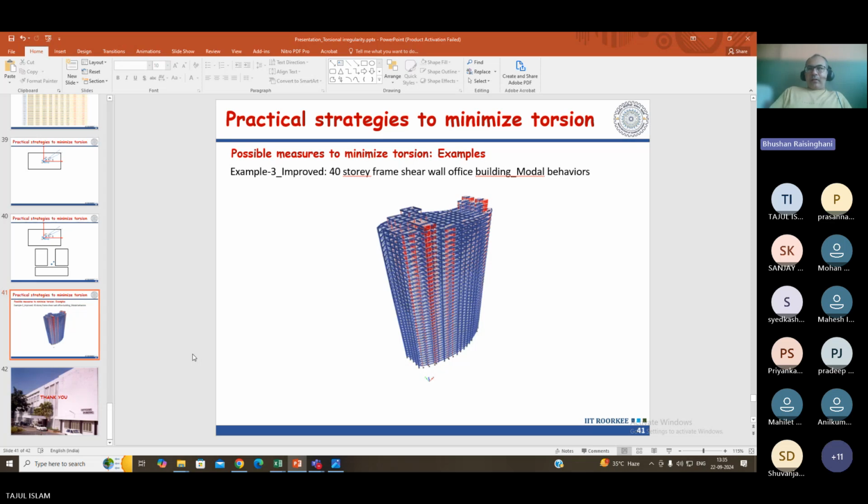I would add this. Our beams and columns are 2D elements, and the shear wall, though taken as a, let's say, pier, mostly works as a 2D element, not as a 3D element, right? That's why the third direction force is not considered for design. So if you give a specific instruction that the third direction force is to be considered for design, then only it can take effect. Otherwise, it will convert the third direction into the two principal directions, the additional shear. That needs to be ensured, because that is the confusion.